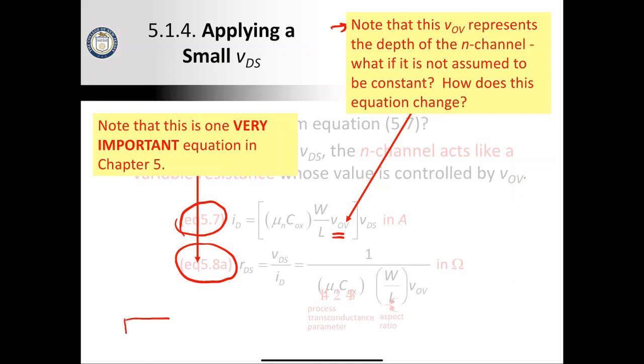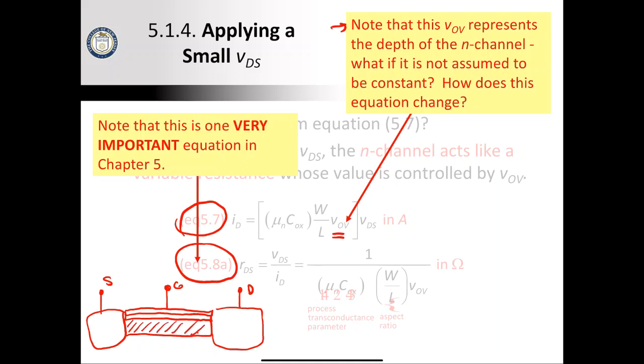Right now, if I were to draw this, I have my channel, I have my dielectric layer, I have my plate, I have the gate terminal, I have the well, I have the other well. Sorry, I'm running out of space. That'd be my drain, that'd be my source. So source, drain, gate. Now, this right here is a rectangle. The reason is because the strength of the electric field over here is the same as the strength of the electric field over here.